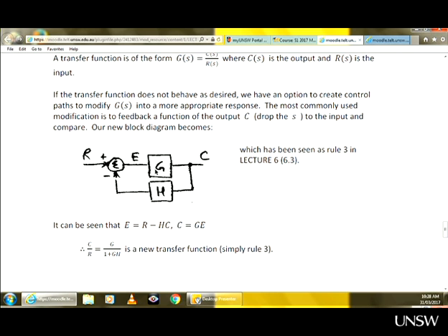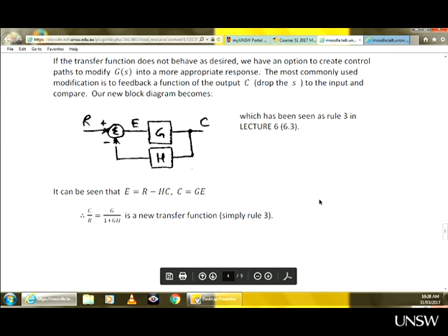If you apply a feedback loop like this, a negative feedback loop, this control loop should also take care of that, should reduce the effect of the deterioration of the system. Now, the whole thing is sensitive to changes, of course. But what that page is saying, effectively, is once you have a control loop, the changes in the system or in the plant have much less effect than changes in the sensor.